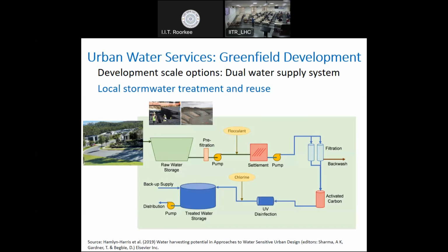So depending upon the quality, all those modifications will be site specific. As such, there is no one solution for everything. So that has to be taken into account: the site specific conditions, the quality of the stormwater which we are collecting. At different points in the system, we can have either coarse particle removal, GPTs, gross pollutant traps.